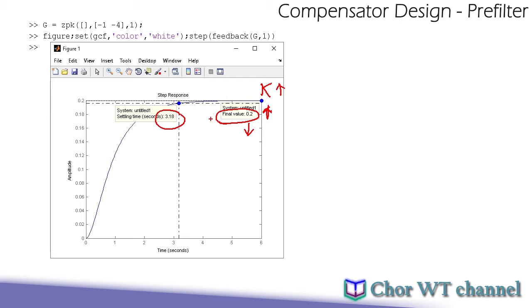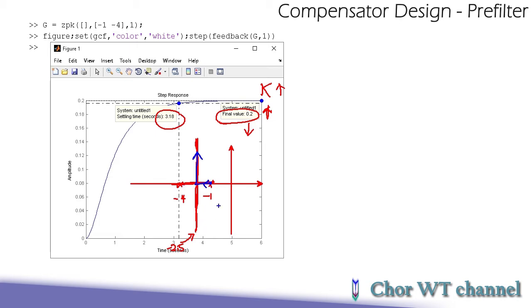What we observe over here, if let's say this is the root locus, I'm going to have 2 points here, which are -1 and -4. And then basically this is how the root locus looks. If this is a point of -2.5, and I try to increase my gain, my roots will run from this point, go to here, and then go up. Of course, the other complex conjugate will go down in the other direction.